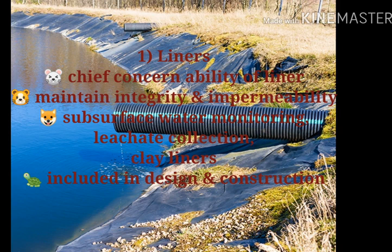Liners. Natural and synthetic liners may be utilized as both a collection device and as a means for isolating leachate within the field to protect the soil and groundwater below. The chief concern is the ability of a liner to maintain integrity and impermeability over the life of the landfill. Subsurface water monitoring, leachate collection, and clay liners are commonly included in the design and construction of a waste landfill.